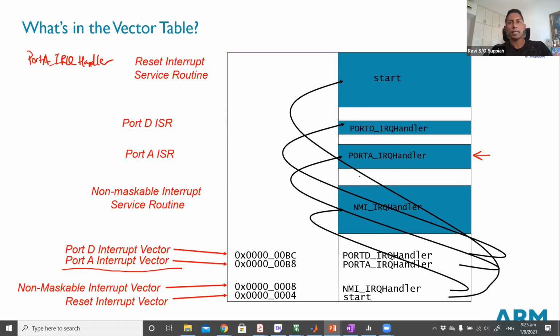Because the linker has already set aside a space for all your code, and as you write your code, the starting points of these various functions will get shifted around. So we do not know the exact starting point of the handler. Only when you compile and link your code do you know the address, based on the mapping to the memory space.